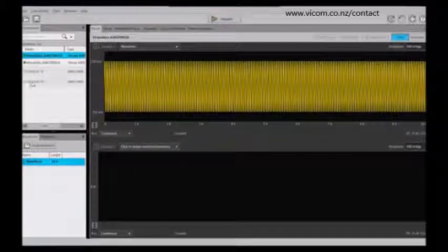You can only talk to one of the instruments at a time, so you would go in and pick the instrument that you want to send waveforms to, and then just drag and drop that into the display, and that would send the waveforms to the actual AWG. When you're actually connected to an AWG, then all of your functions work similar to what you would do on the actual hardware of the instrument.